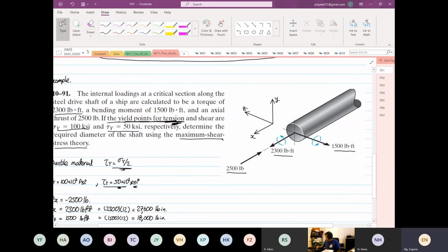Given the loading condition, the axial load is running in what? In compression. And for this bending moment, at one point of the shaft, the maximum loading is going to be compression. It will not be equal to what? Tension. I repeat again, over here, our axial load is in compression. Our bending moment, at a single point of the shaft, will induce compression also. So the maximum stress region is not in tension. It's going to be compression because of this.